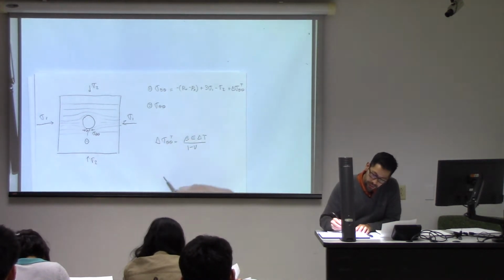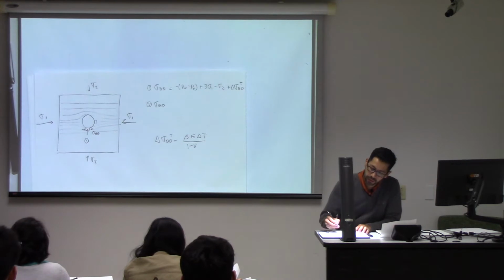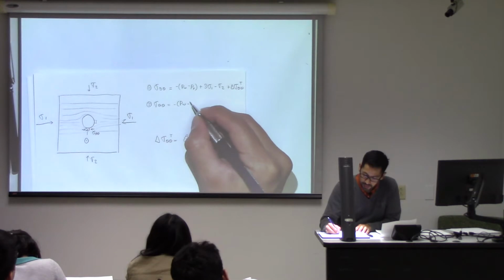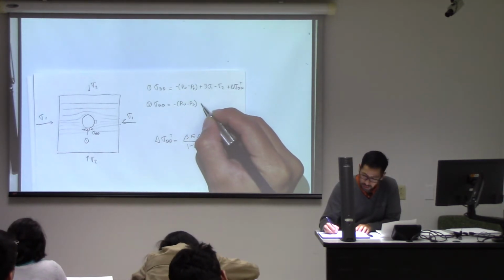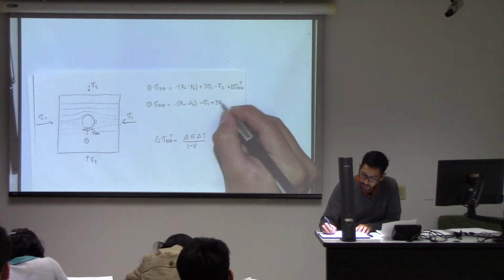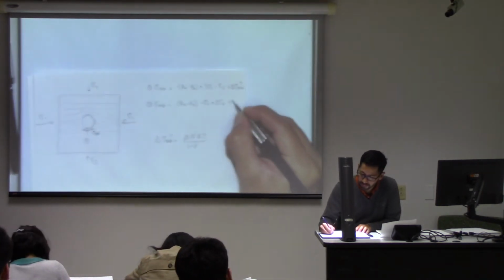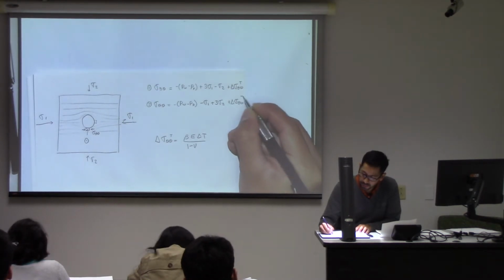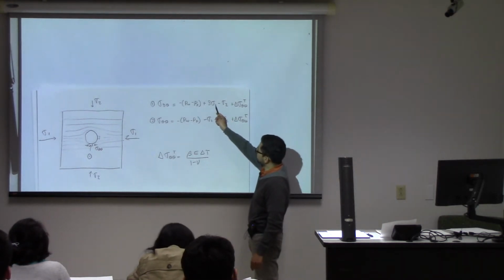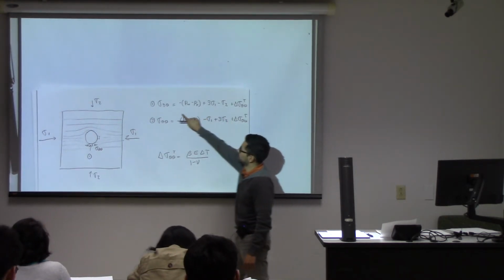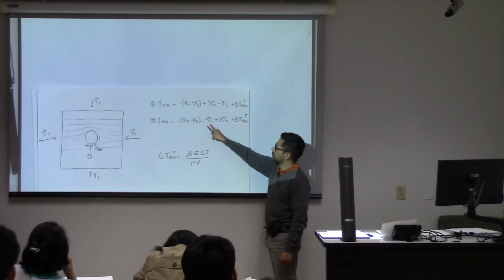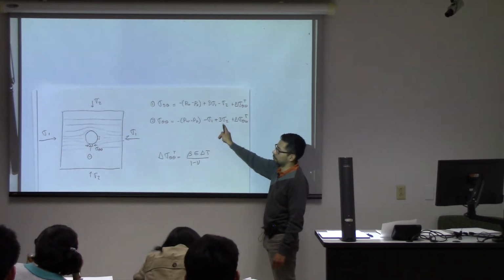But also you can calculate the hoop stress at this location. And at that location, the equation for that is going to be similar to the one above, but with a different coefficient in front of those principal stresses. And notice that now this one is larger than that one, right? So now we have more compression here in the breakouts. Now this one goes with a negative sign. This is the maximum stress, and this is the minimum.